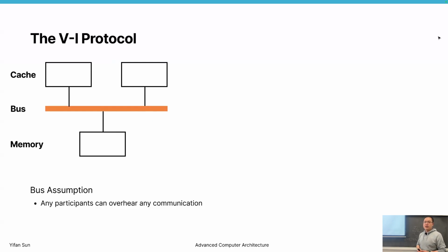With all-to-all connections, this cache would need to send to the memory and separately to each other cache to achieve the same effect, which is less efficient. So there's always a trade-off between using a bus or not. The general trend is not to use a bus for high performance designs, and to use a bus only for efficient systems. Okay, so here is a bus.